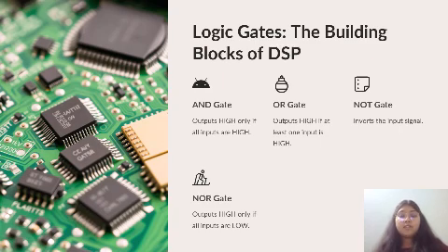Implementing basic DSP operations with logic gates. Signal addition in digital systems: adding two signals is done using XOR gates along with carry logic, as in adders. This allows the system to add binary numbers representing audio signals quickly. Signal multiplication: this can be done by repeatedly adding one number to itself and shifting it, based on binary multiplication rules. Logic gates can manage this addition and shifting.